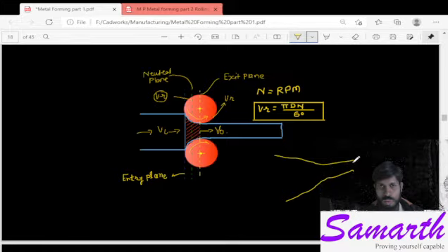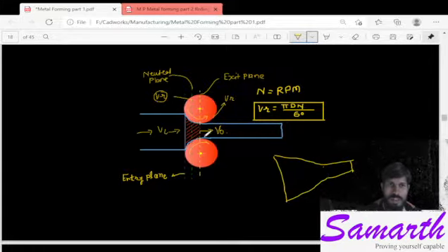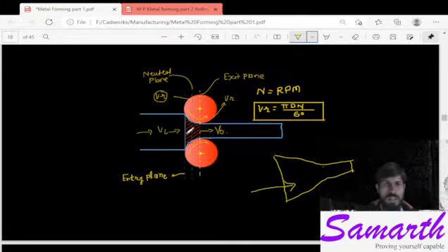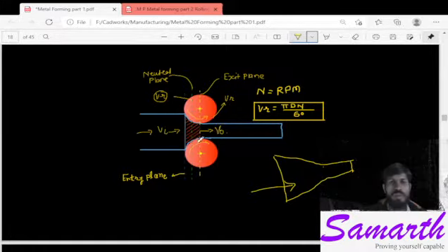If it is a nozzle-like structure, as there is a flow of material, this metal is flowing in this direction, then the volume, let us say mass flow rate, is constant, so the velocity at this point will be lesser and the velocity at the exit will be greater. Similarly it happens here because this shape is like a nozzle or throttle, you can see.